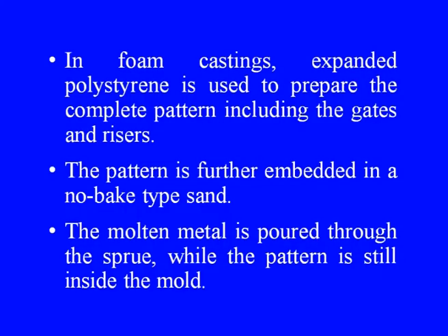The pattern is further embedded in a no bake type sand. The molten metal is poured through the sprue while the pattern is still inside the mold. The heat of the molten metal is sufficient to gasify the pattern and the pattern progressively gets displaced by it.